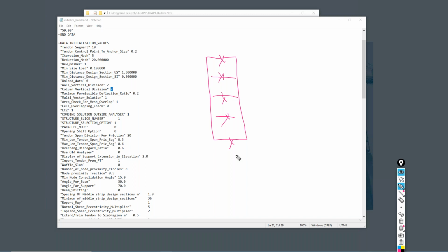If you had to create a restraint at a node, then this would not work because I can't really create a restraint at this node without having a reference plane there. So there you would have to create the 5 different levels, and then you might have to apply some sort of restraint or support at the node. It could be a spring, it could be a pin, fixed support, whatever you require to simulate the need for the small p delta.